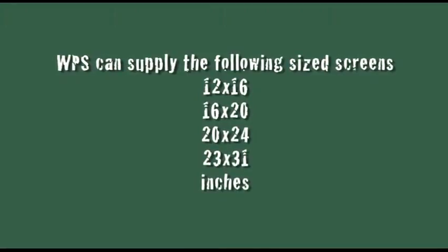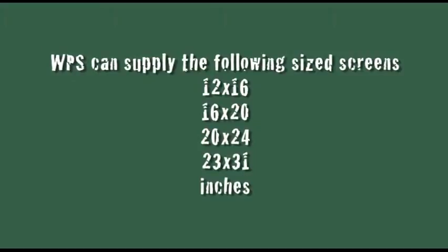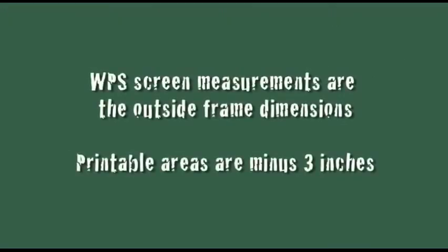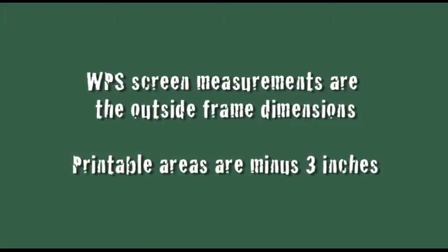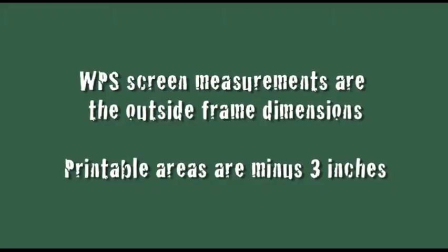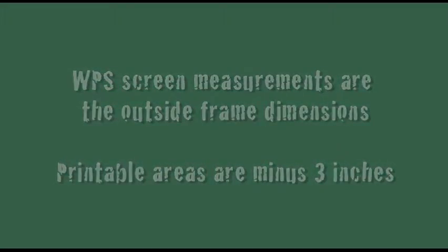The mesh count will depend on what substrate you are printing onto, what ink you are printing with, and how detailed your artwork is. The mesh counts can range from 15T, which would be used for glitter printing or highly absorbent surfaces, to a 200T, which would be used for extremely fine and intricate lines, hand drawing and photographic work.